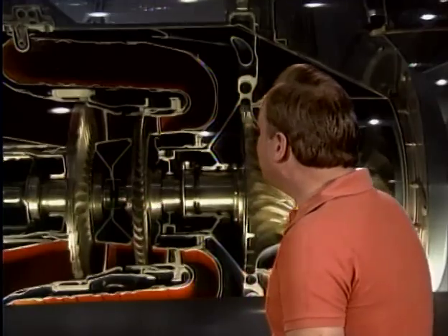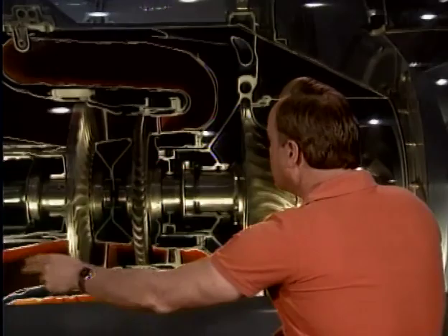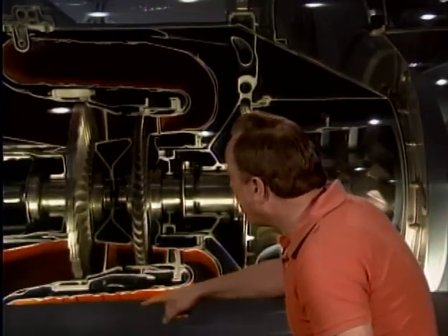Exhaust gas temperature, what's it used for in a turbine engine? Well, it provides a relative indication of the turbine inlet temperature. That makes sense. Even though you might be measuring exhaust gas coming out the very back, it gives you a relative or comparative indication of the turbine inlet temperature, and that's really what you're interested in. So EGT is kind of an approximation of turbine inlet temperature.